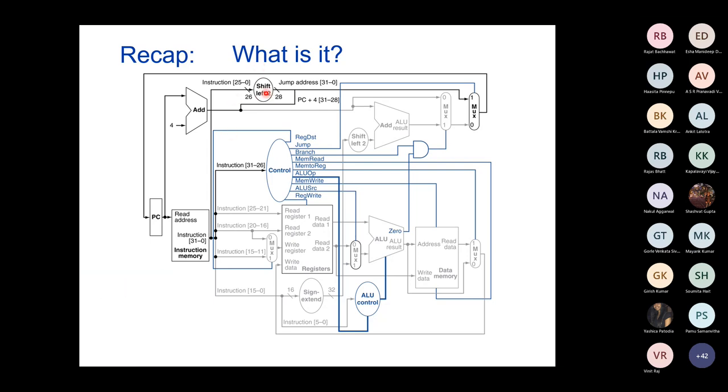So you can see here, this is the portion where the jump instruction has been taken care of to find out the target address, and this is the logic that takes care of the branch address whenever the branch is taken, and you have all these AND gates and so on, all kinds of data path. This is a primitive processor or data path, you can say, for implementing these basic instructions: load, store, add, subtract, and, or. And you remember that this ALU also realizes SLT, set less than instruction, branch equal, and jump.